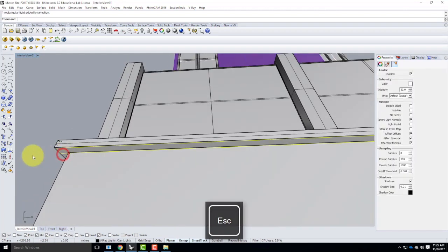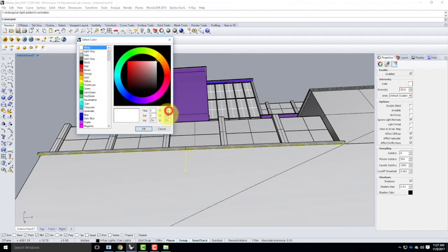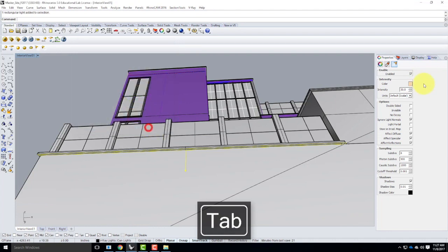Now, when I look at the rectangular light itself, again, the settings are based on the proportions and the size of the light. There probably is some mathematical way of finding out what that should be, but for me, the easiest way is to just do some guessing. So I'll set this up. We'll do the color first. I've got 255, 214, 170 for my color.